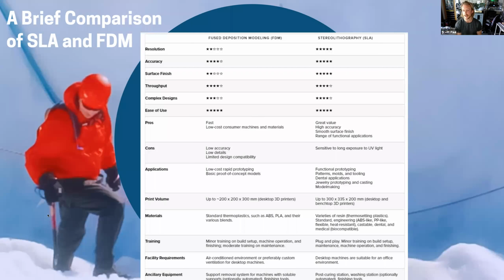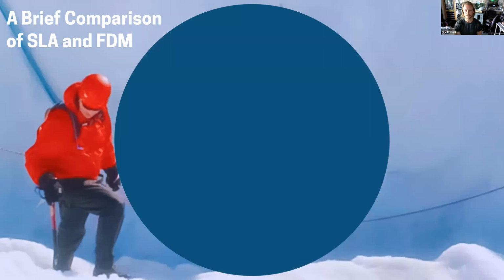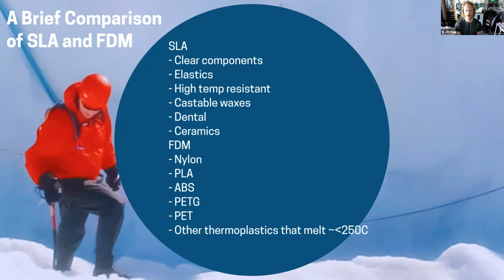And that's, again, part of the curing process. The XY resolution of an SLA printer is, I want to say, well below 100 microns. And so the spot size is really fine. And then the layer resolution is also less than 100 microns. So you're not going to see those layers. Let me show you some pictures, which are up next.